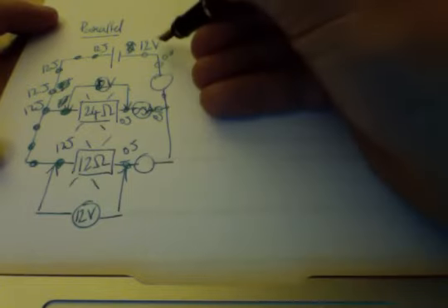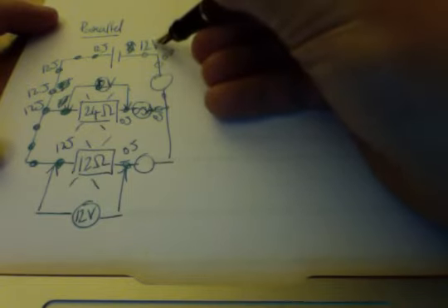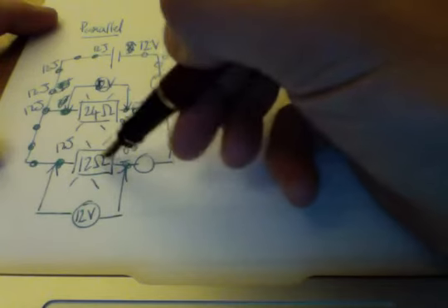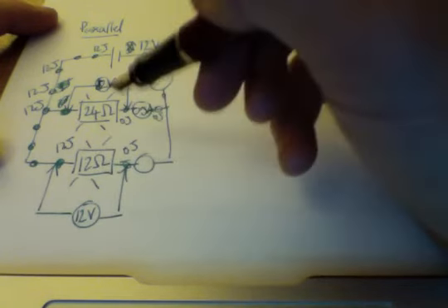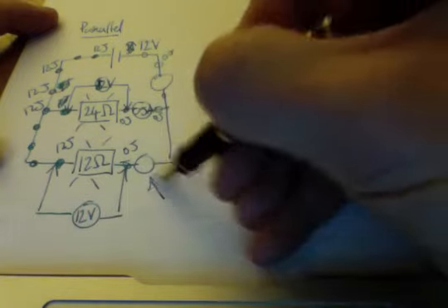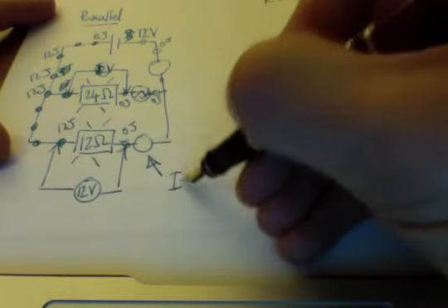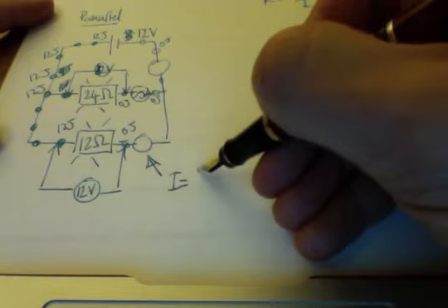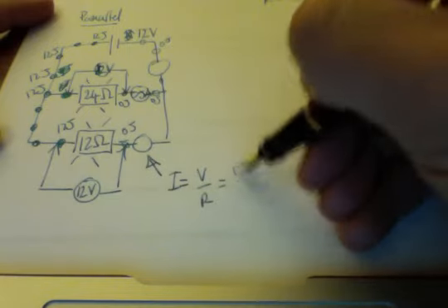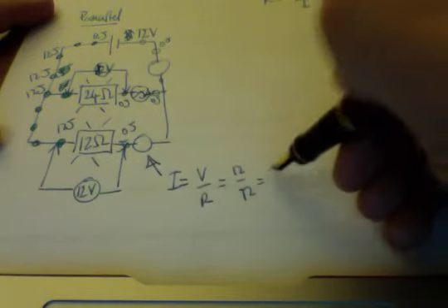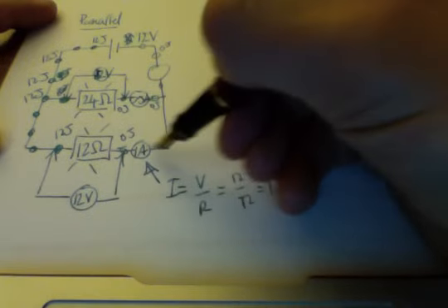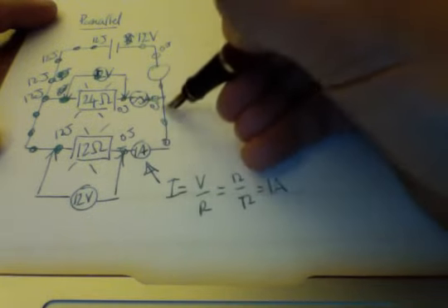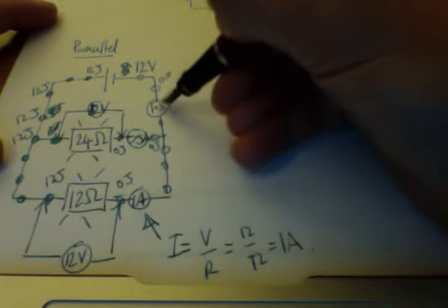Okay, you can say to yourself, if you like, that 12 volts, 12 ohms suggests that you're dead on the right ratio to suggest that 1 amp is needed. But let's work this out a little bit more accurately. Current is going to be voltage divided by resistance. 1 amp. And so therefore, if 1 amp of coulombs are coming up here, and 0.5 are coming through here, this must be 1.5 amps.